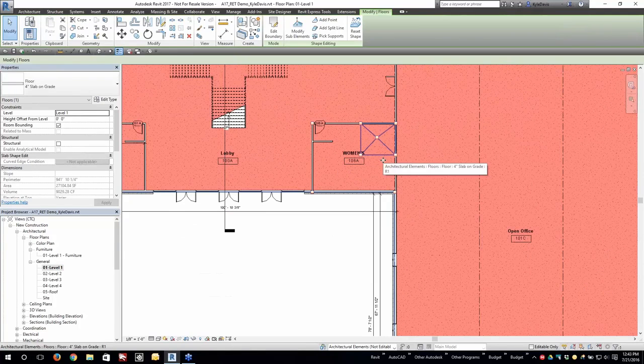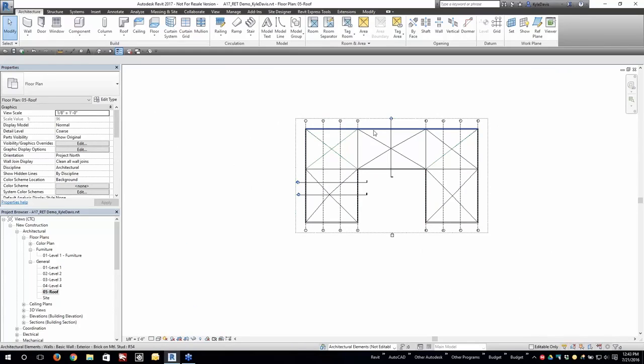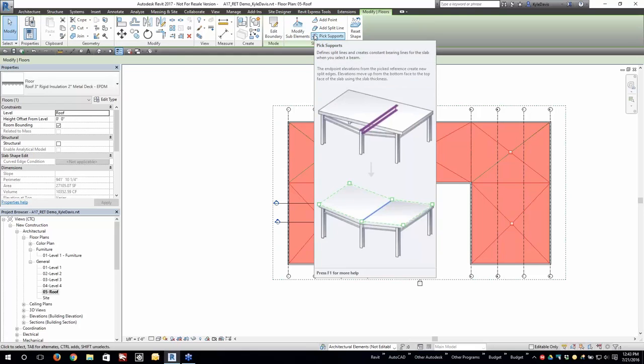Now again, this is only available for flat roofs and flat floors. It's not available if you put any kind of slope to the roof. In this example, this is not a sloped roof, but if I wanted to slope that roof all the way back to the bottom and have it be at an angle, this option won't be available if you have that pitch slope to it.